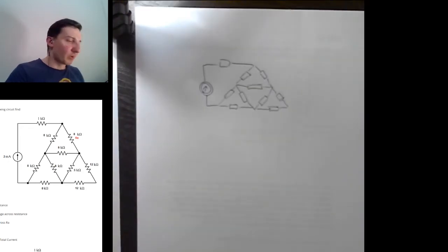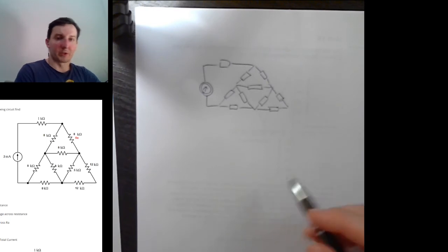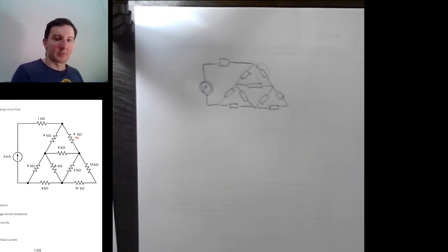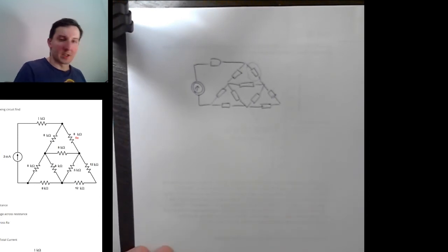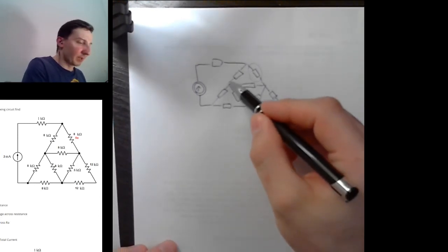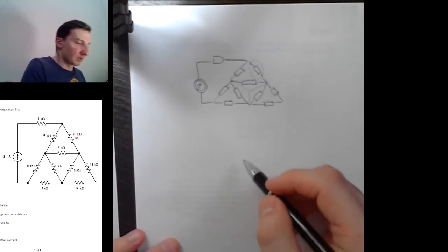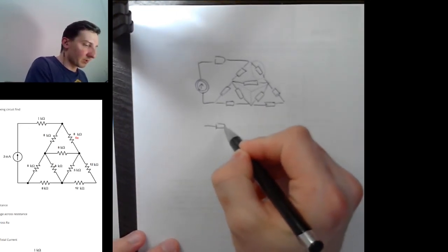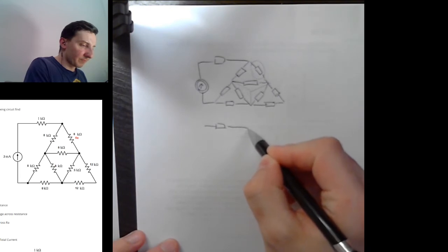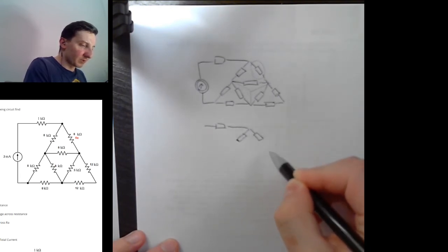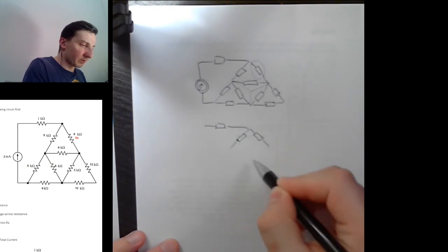Now when we want to calculate the voltage drop on a single resistor, which is this one, we can use the delta-Y transformation in different places. So we can use it right here. So let's try to redraw this scheme. These two resistors are exactly as they were.